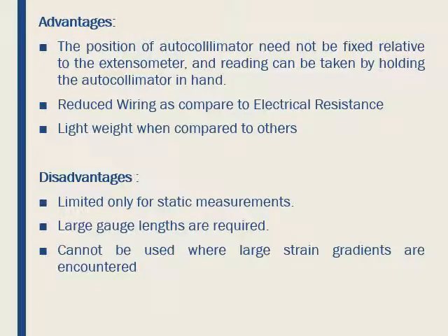The advantages: the position of the autocollimator need not be fixed relative to the extensometer, and hence readings can be taken by holding the autocollimator in hand. These are best suited for static tests. Reduced wiring compared to electrical resistance, and lightweight compared to others.